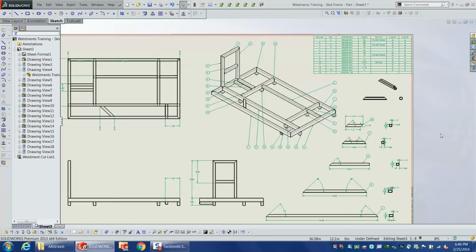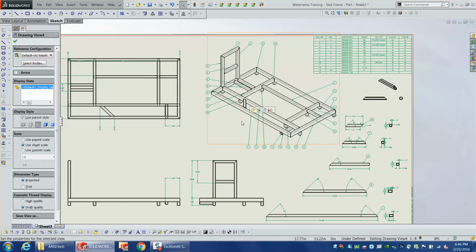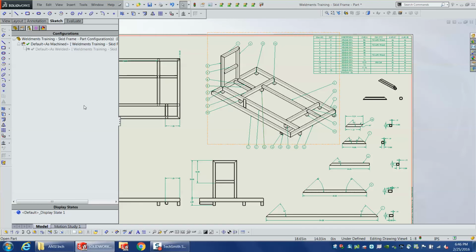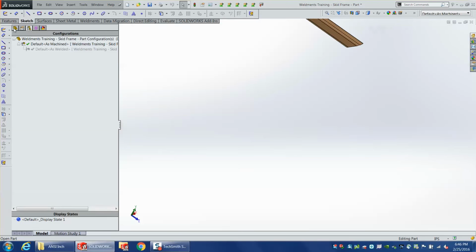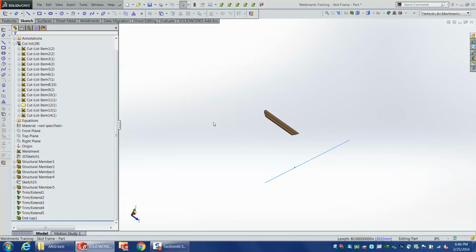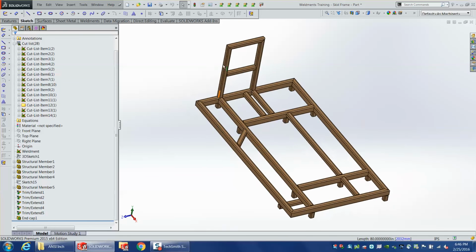thought someone told me that SolidWorks came up with a way where you were going to be able to actually remove the components from the weldments. And I was misinformed. You can save the bodies as parts and keep them linked. So he's bringing up a point too. You can actually save these bodies out as parts and keep them linked if you need them for some reason, even a group of them together. So if you need to export them for laser cutting or something like that, you can save them as parts.